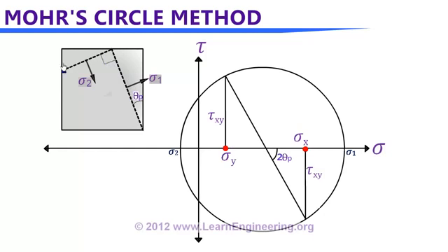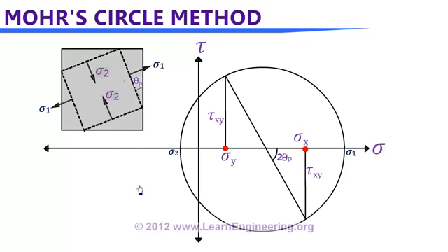And if this system has to be in equilibrium, there should be equal and opposite stresses to balance this force. So the complete principal stress diagram will look like this, like a square, where these two stresses and these two stresses balance each other. And one interesting thing to note here, if we check shear stress values at the principal plane, you can note shear stress values are zero over there. Means on principal planes shear stress doesn't exist.